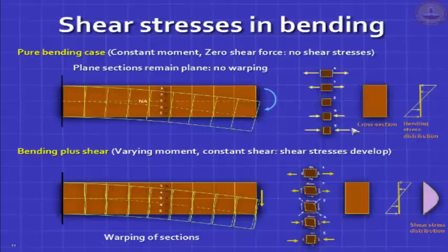It's also important to note where the shear stress is maximum. In a rectangular section, you'll find that it's a parabolic distribution. This can be derived, with a peak exactly where the bending stress is 0. Very interesting. Where bending stress is 0, shear stress is maximum. Where shear stress is 0, bending stress is maximum.